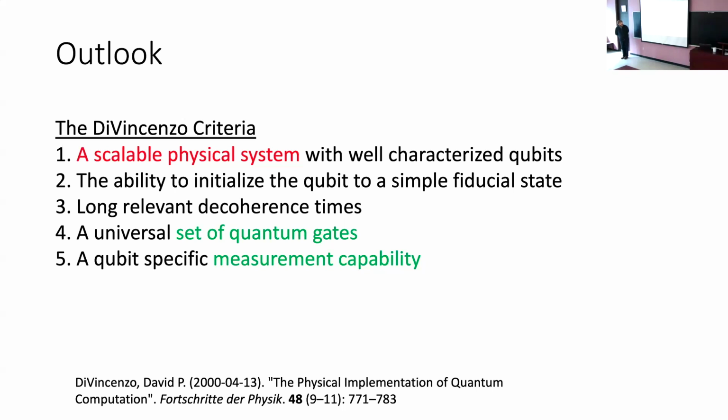The difference is that in addition to RF control, microwave control, and coax cables, we have a lot of really low noise DC lines that have to go down. So each experiment has something like, on a quad dot device, maybe 30 or 35 really low noise voltage sources that are biasing all of those gates. So people are thinking about ways to share voltage control over all those gates, such that you can find architectures where that scales reasonably well.